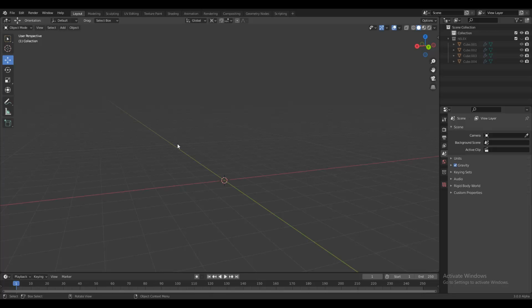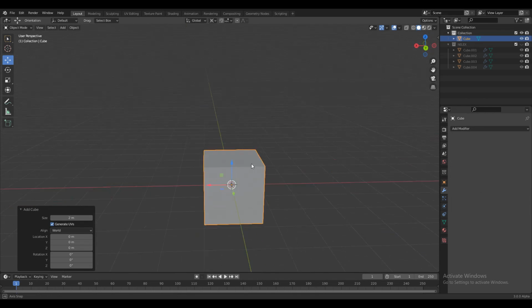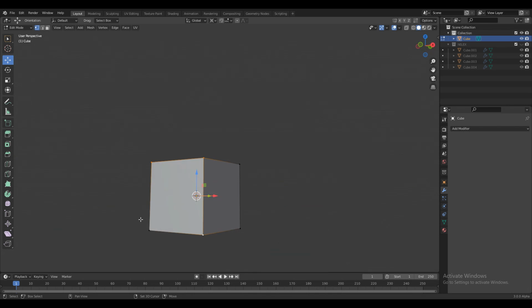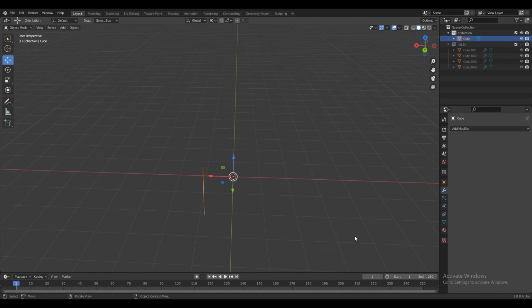To make the Helix design, we will start with the cube, so Shift A and then add a cube. Then you need to select the corner vertices and then Ctrl X and delete those vertices. We want a 2D vertical edge there.